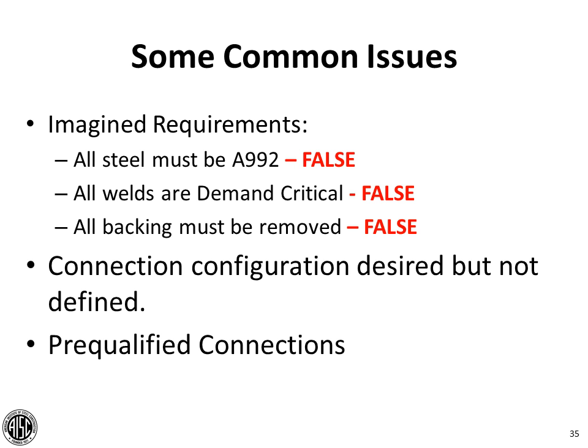And then connection configurations desired but not defined. We'll see that in a little bit. This goes back to the Code of Standard Practice as well, where any restrictions on the connection configuration need to be shown. And then finally, we'll talk a little bit about pre-qualified connections and some of the problems we see related to those.